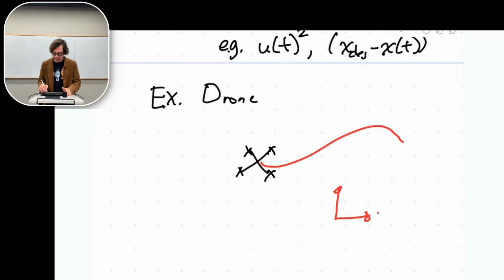Here's just some x and y trajectory, right? And your prediction has all of these points along the trajectory, those little points. That's the trajectory where it thinks it's going to go. It runs that trajectory optimization and says, great, I'm going to execute the first step of that trajectory, and then rerun a trajectory optimization with my dynamics.